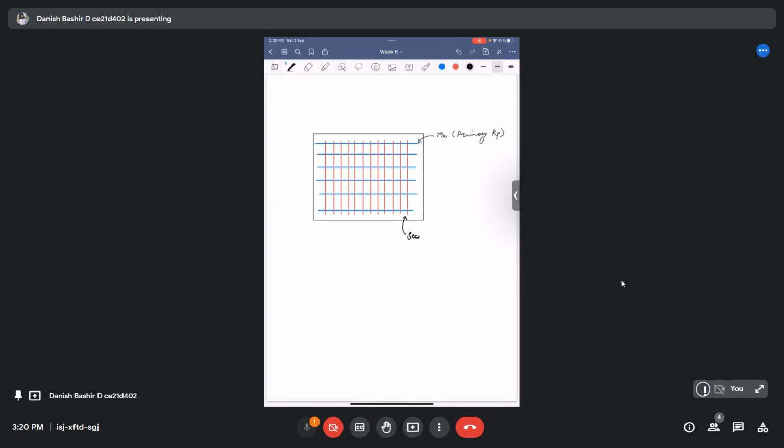Secondary or distributed reinforcement. Its main purpose, unlike the primary reinforcement, whose main purpose is to take the bending moment, is to take the stress due to shrinkage and temperature change.